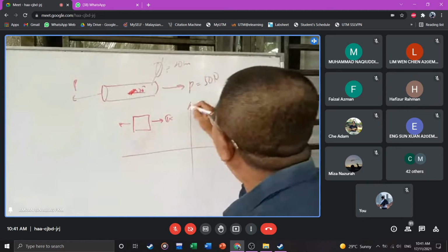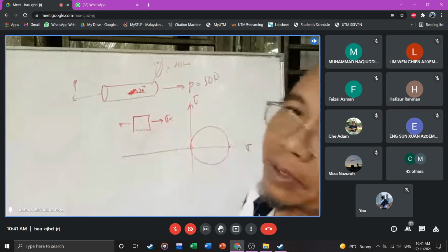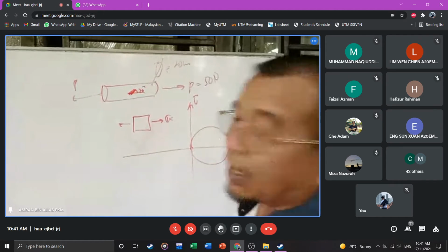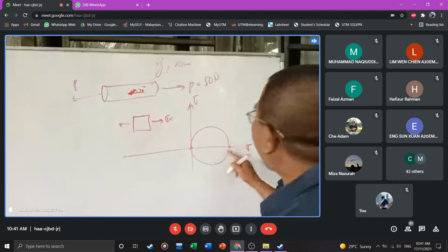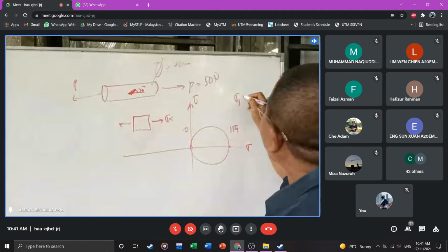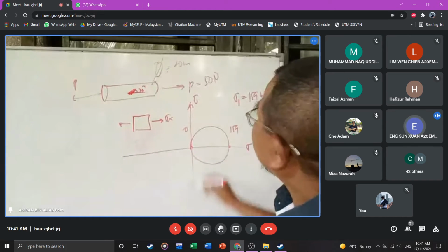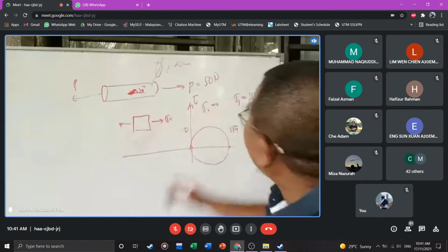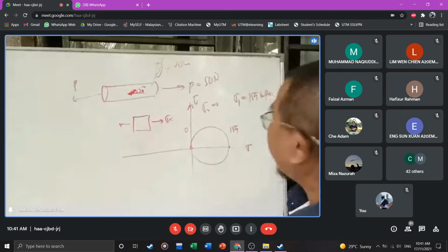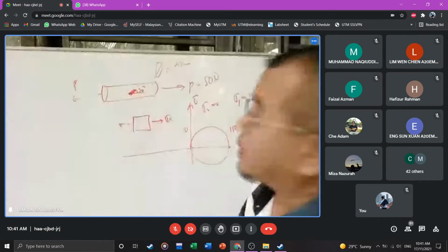This is sigma. This is tau. 0, 0 there. You got that one on? Yes. And then you got 159 and 159 there. This 0 there. This 159 is equal to your sigma 1, which is also 159, right? Yes. Your sigma 2 is 0, right? Yes. Okay. When you finish that one, can you convert into strain?